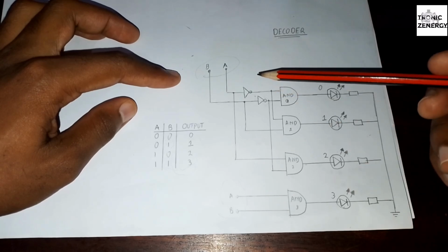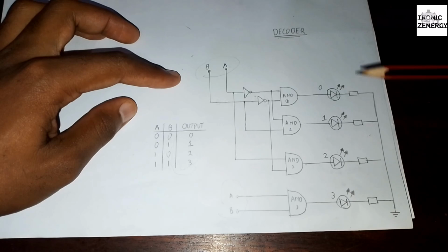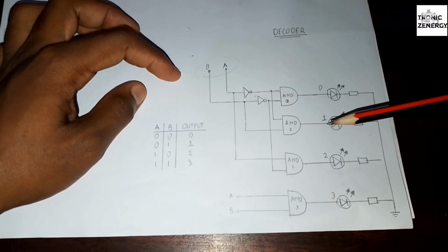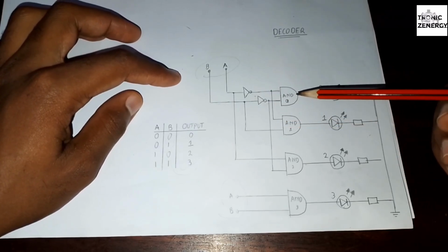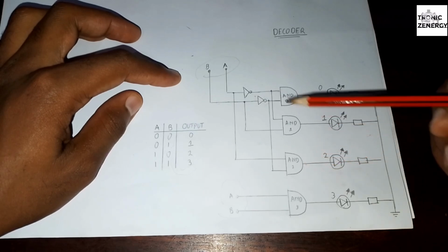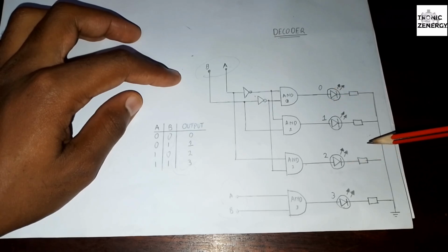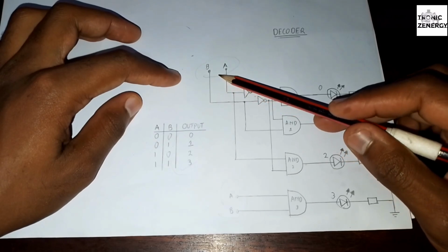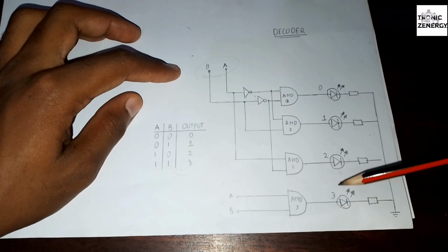So for mine, that's a simple one. It's going to convert binary into numbers, and that's basically what this 2 input 4 output decoder will be doing. It's a simple circuit. It entails 2 input AND gates, 2 NOT gates, and I've used 4 LEDs just to show us what we are doing inside. This you can take as a control. We are going to be controlling this part, and it's going to show us the numbers from 0 to 3.